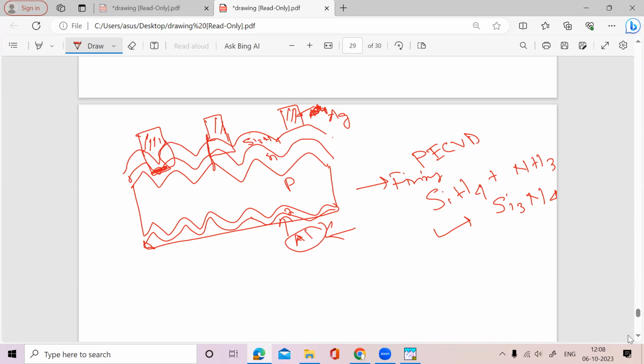When you go for firing, this n-type layer is not converted into p-type, it will convert into p plus. So for this reason, I am telling this firing is so crucial. Why? Because of these two things at a time.